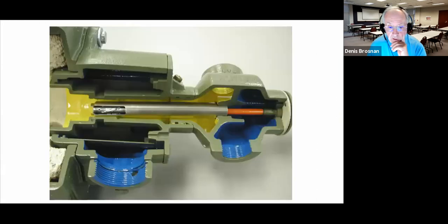You can see it a little better in this cutaway. Particularly, you can see how the air plenum surrounds this burner housing, and air is injected through these openings into the burner. But now you can more clearly see where the gas comes in if we're operating only on gas through the gas line into the burner. But if we switch over